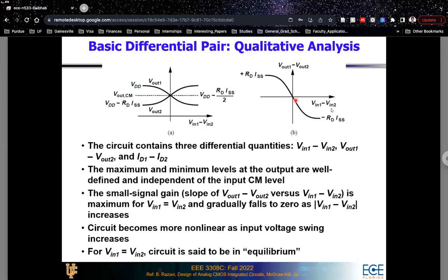Of course, there are other non-idealities or second order effects because of which it will not follow the square law model exactly, but you can approximate the behavior of the transistor with the square law model that you have used in your homeworks or in your exams. Now, of course, if it is squared, then it is nonlinear because you know a linear expression is something such as y equal to mx or output equal to a times input.